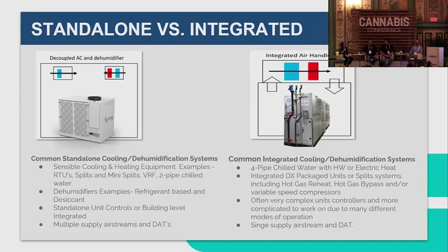The units are going to run more consistently, and so that gives them some longevity as well as efficiency. So less cycling with an integrated system than you might see with a standalone system. Yeah, and the standalone system has the benefit of having more units typically in the room, so you've got more redundancy. It's a little bit more maintenance, but there is that trade-off that a lot of people find attractive. Sure, trade-offs as in anything.